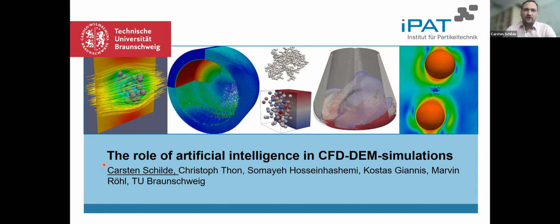So the normal stress energy is quite easy. You have the relative velocity and the mass. The relative velocity during the contact, just when the contact happens, may be damped due to the fluid before. So if you have a lubrication model, of course, the velocity is damped, but if you have a contact, you're using this relative velocity times the mass, velocity to the power of 2, and times the mass of the grinding media.